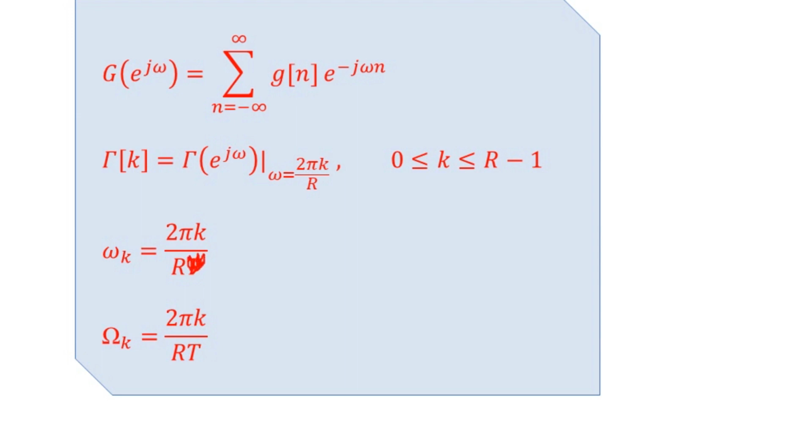For making the interpretation of the results of DFT based spectral analysis in the correct form, let us consider the frequency domain analysis of the sinusoidal signal, or in the discrete time domain you call it a sequence. The infinite length sinusoidal sequence that we had considered initially to be g of n, in the first equation you see on the right hand side here.